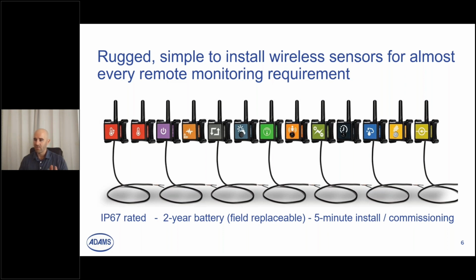So they're all battery powered. They're taking that 2-minute or 10-minute heartbeat, I call it, but a sample every 10 minutes, and that's what's giving you that 2-year battery life. In certain scenarios, if we need to increase or decrease that heartbeat to sense a little bit more frequently or less frequently, that directly affects the battery life. If you're sensing less frequently, you're increasing battery life and vice versa.